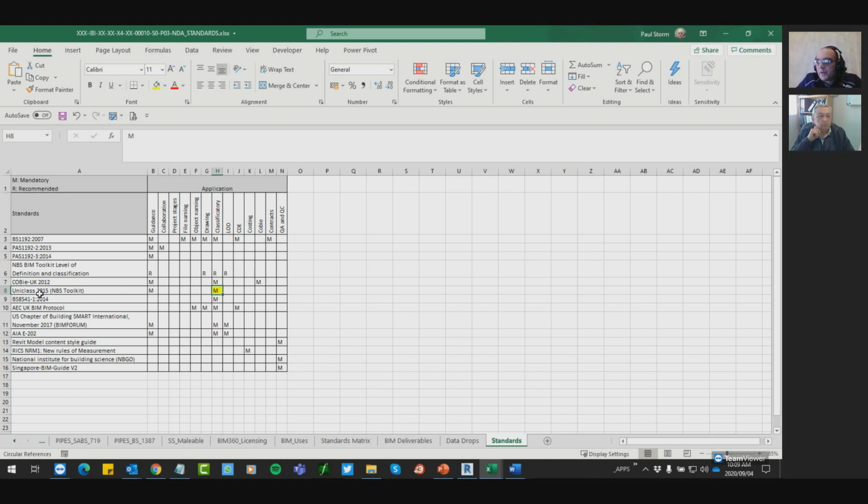How do you use Revit to comply to some or other standard? It does not need to be unit class. It could be some different standard, and that is within the classification of the elements. This is important downstream because from a design perspective, you are going to hand over to a contractor most probably, and the contractor will use this coding not only to do costing, but also the planning of stages during the project.